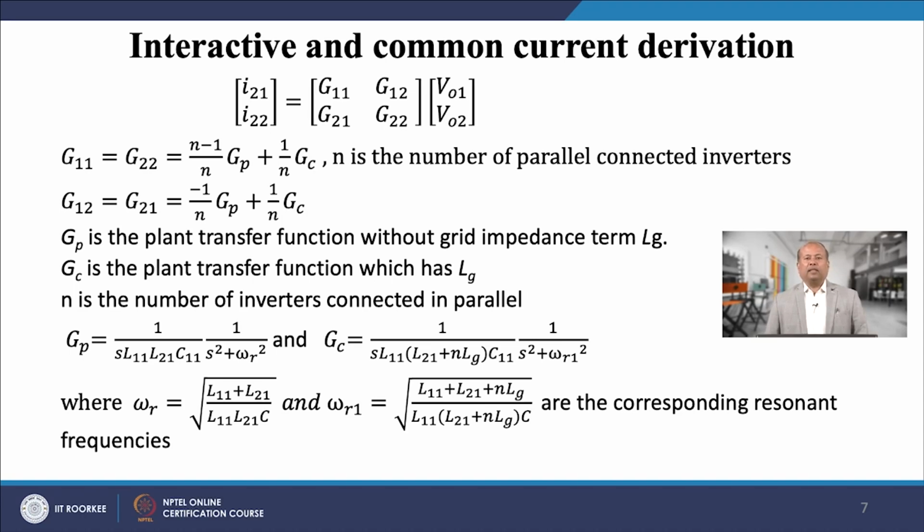These are basically the oscillatory currents flowing between the inverters. So, just to go into detail, you have two inverters and four current components, two from each inverter. Two components are responsible for power flow and two components are responsible for oscillatory currents flowing between the inverters.